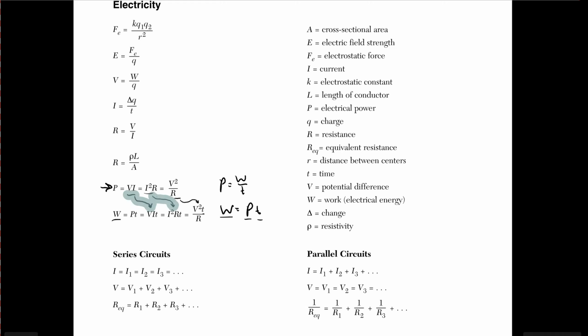But so I could show where all the different power equations come from. And I said that we used Ohm's law. So Ohm's law, as you remember, is this one. So how can we use that to derive those weird looking formulas? Well, we know that power is the voltage times the current, right? So all you have to do is manipulate Ohm's law.